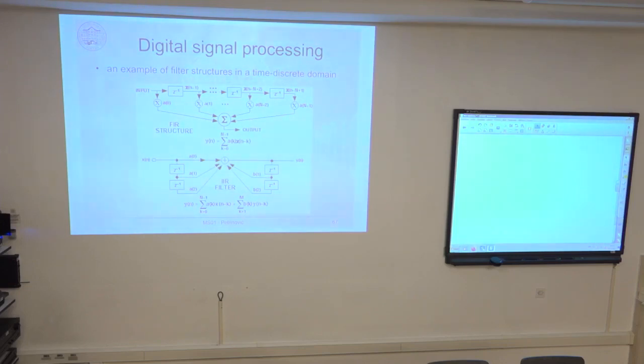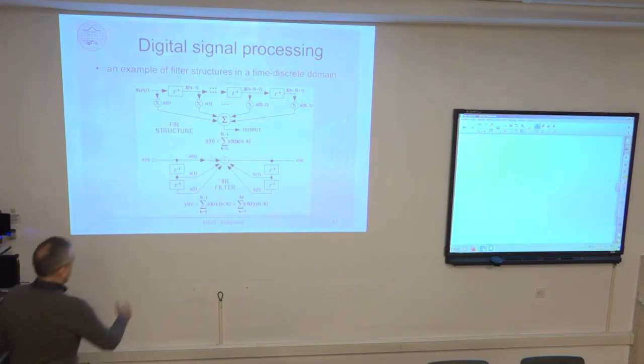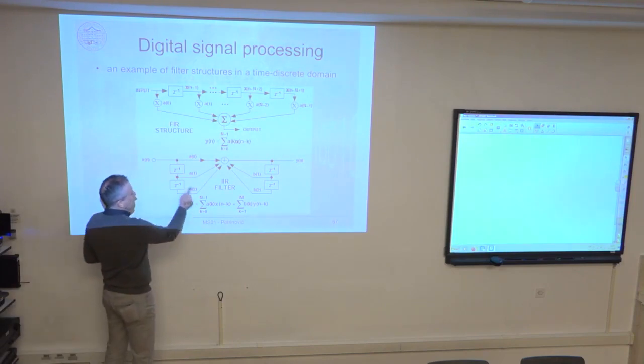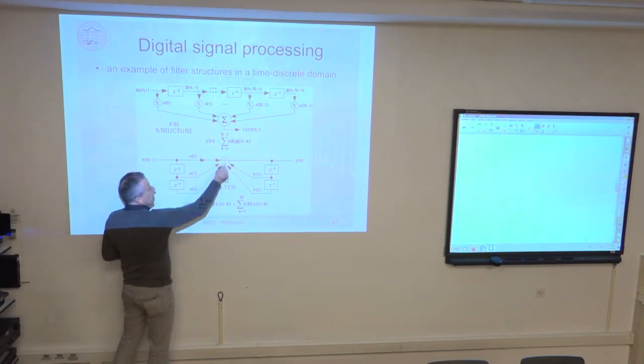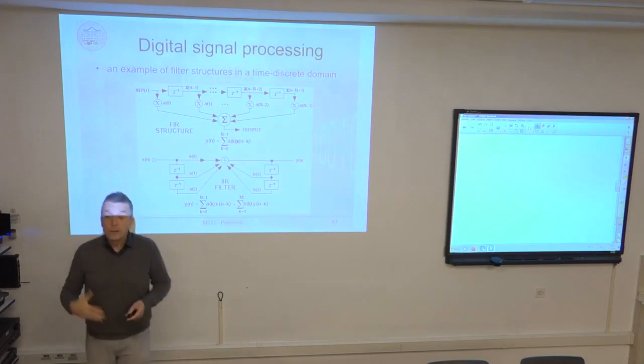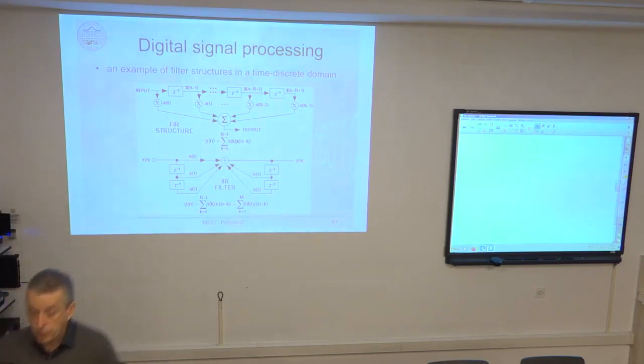So that was the basic idea when introducing these DSP processors, to have an instruction that is capable of performing one such multiplication. For example, this value here times A of 2, and addition to the current accumulated value in this summation. So addition and multiplication are all performed in a single cycle as one instruction of this DSP processor.